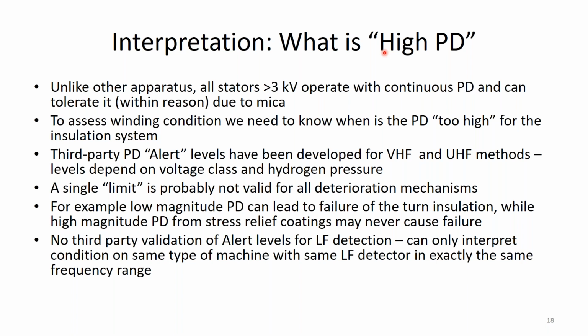If the bearing vibration is above certain limits in displacement or acceleration or whatever, for specific types of bearings, we know that if the vibration level is high enough, that bearing itself is probably going to start self-destructing and then cause a failure. So just like bearing vibration, we've established what's really high levels or low levels.